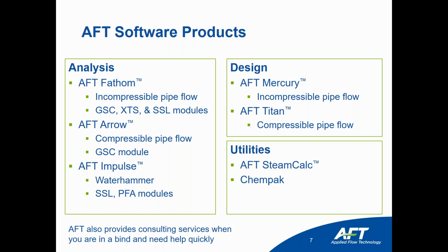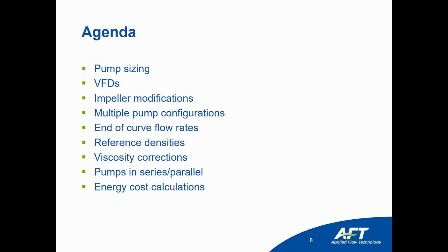All right, so here's what we're going to talk about today. I'm going to go over a quick pump sizing example and how you size a pump, talk about how you would be able to model VFDs and do impeller modifications. I'm going to show a really unique capability where you can easily model a whole multitude of pumps and pump curves within a single pump junction, and that'll be a huge time saver for you.